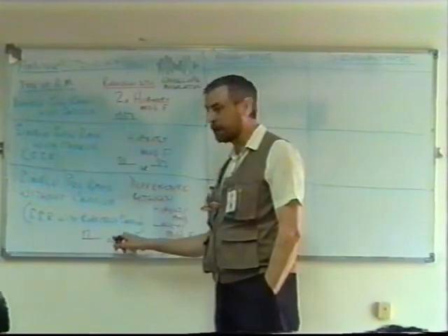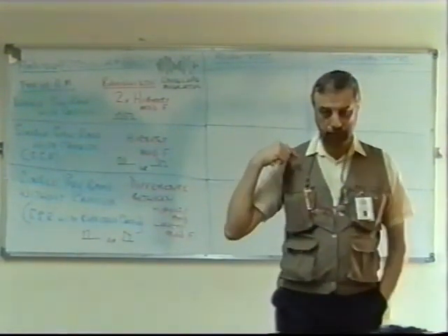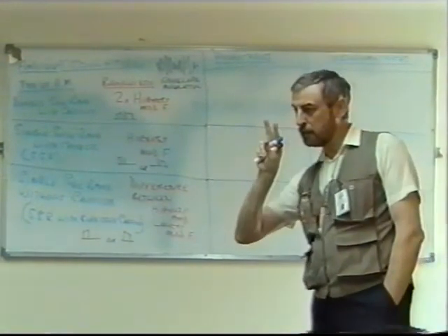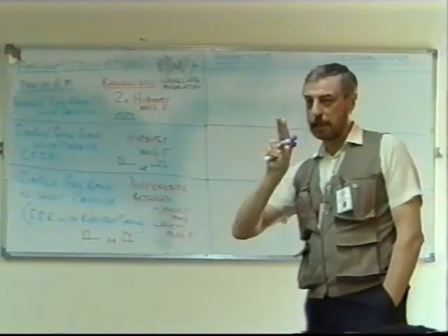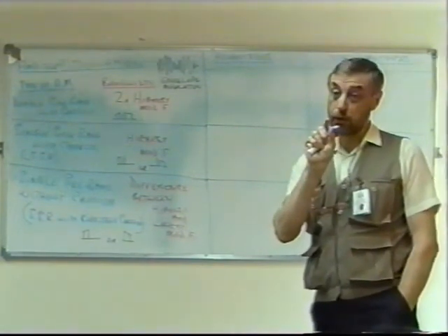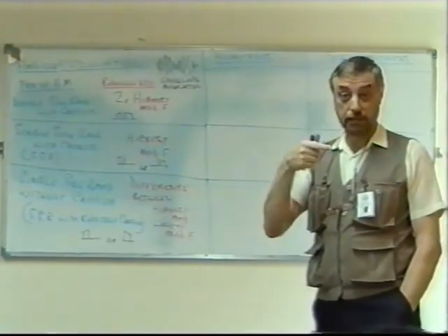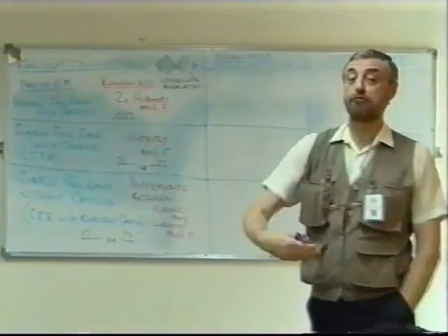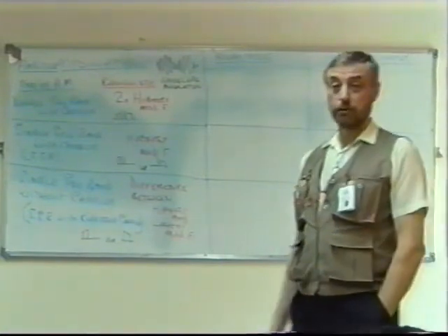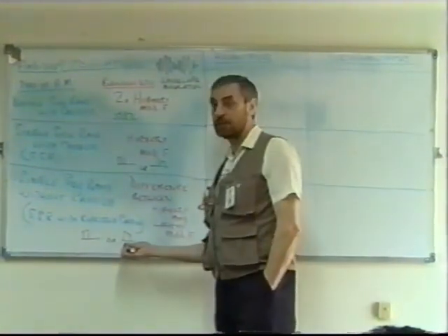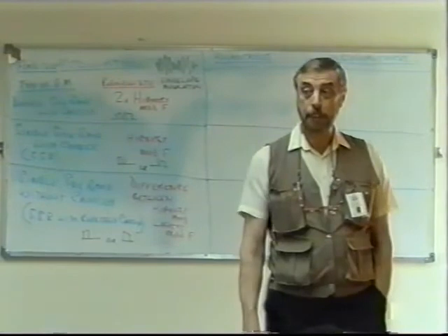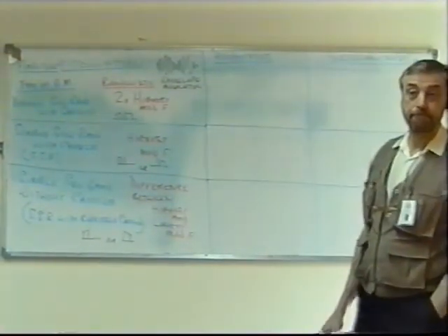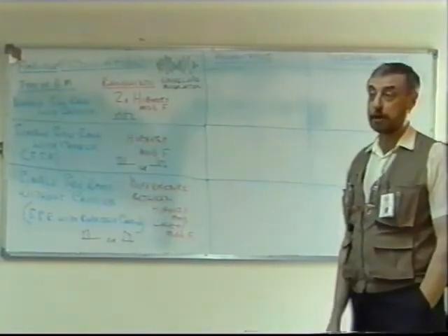That is a very low-level carrier, which the receiver selects with a very narrow band filter and then uses to synchronize an oscillator which generates the same frequency, and that's mixed with the received signal to reintroduce the carrier. So you're right, we cannot really demodulate this without a carrier, but it's not actually necessary to transmit the full carrier. Now it does sound complex, and it is complex.